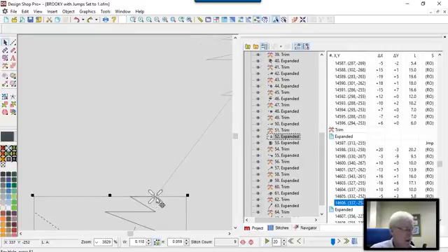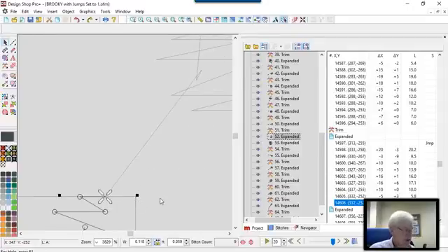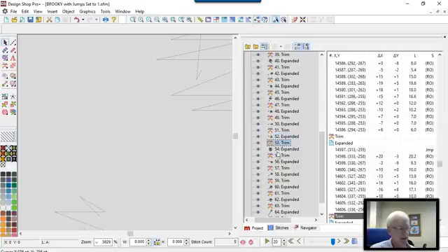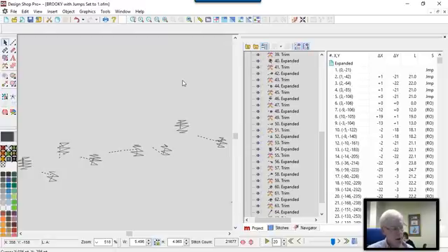Alright, and then I want to go into expanded editing mode, and then I can take this and drag it wherever I want to put it. Boom. I want this to be a tie stitch, and now that I'm between the two elements, I can put a trim in. So now you can see it stitches the element, it trims, and it stitches the second one. So split element is the way to break apart part of an expanded element so that you can force a trim in there. Nate was mentioning earlier, split element is used often, and it can be hotkeyed.